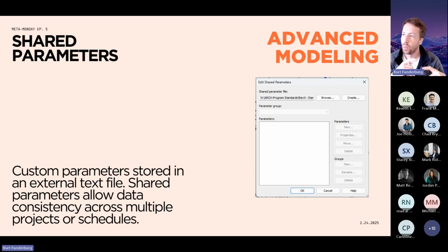And so with our distribution log, we want to show our schematic design, our design development, and our permit drawings. And then when we're done with permit drawings, we issue one IFC set and all those other dates are cleared out. And so to make those consistent across every project that we do now, we have shared parameters which have SD date, design development date, permit drawing date, and IFC date.